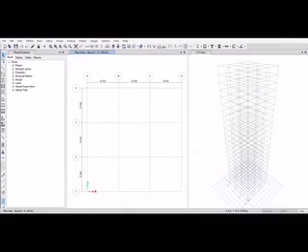For reinforcement property, select modify slash show rebars. Keep the default, set design type to column and change the rebar material. Oh sorry, we have not defined the longitudinal bar materials yet.